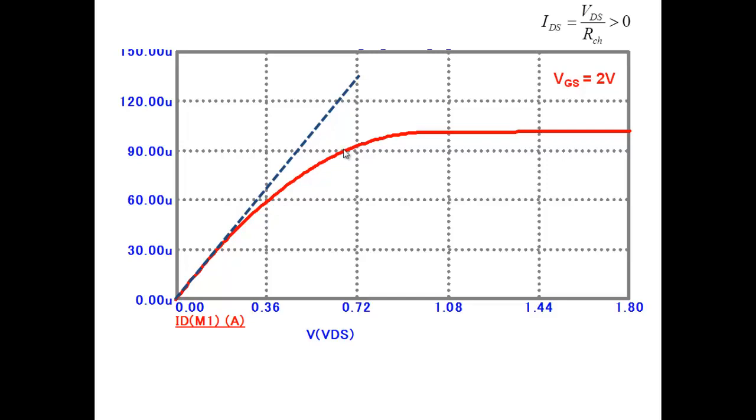Eventually, a stage comes at this point where you see this leveling off, which we call the saturation voltage. It's obvious why we call it the saturation voltage, because the current is no longer increasing. It sort of flattens out. And where does this occur? Where would you guess? At the pinch-off point, in the simplified case where the channel gets pinched off.